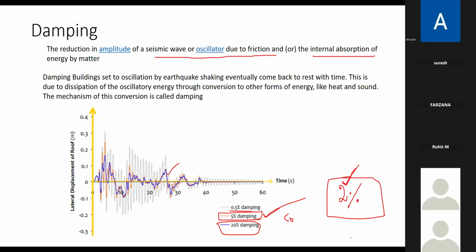Then I go back and continue the analysis and design. This will increase your reinforcement as well as the section sizes, because you decided to design with the torsional irregularity, isn't it? If that is the case, you have to add additional safety factors. So please go ahead.